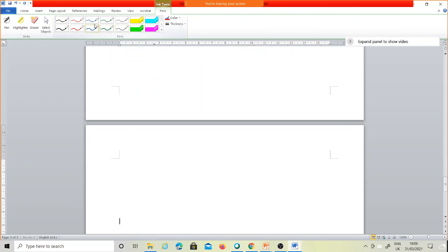Similar way, von Karman integral, you already know that tau in this case is rho u square d theta dx. This form of the von Karman integral is true whether you put the position as 0 or at w, so not necessarily we need to put the 0.